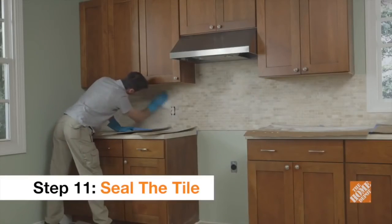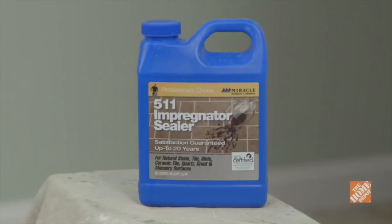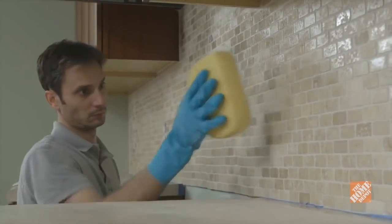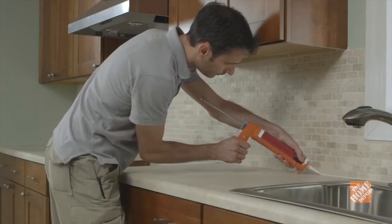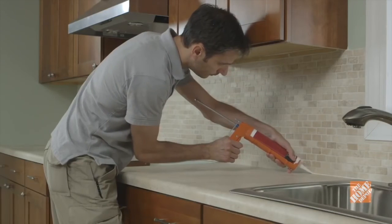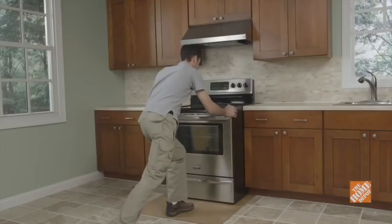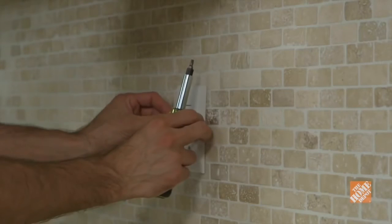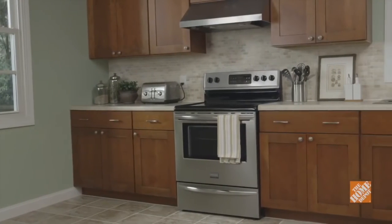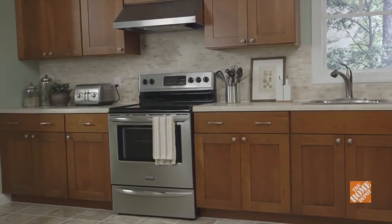Once the grout is fully dry, usually 24 hours to 3 days later, you can apply grout sealant to protect your backsplash from staining. This is the final step in the installation process. After the sealer is dry, you can add a small amount of latex caulk to the base of your backsplash where it rests against your countertop. Replace your appliances and cookware and restore the power to your electrical outlets. To maintain your backsplash, wipe it down occasionally with a kitchen or glass non-acidic cleaner to keep it looking great.